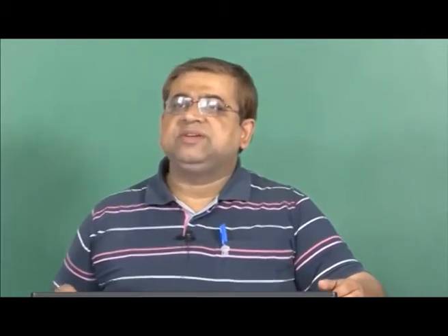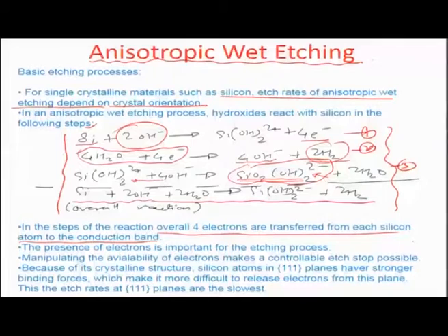So whenever we are performing wet etching using hydroxide chemistry, there is a possibility of eventually the 111 plane to evolve. So let us say if I started in a certain direction, let us say this direction right here is the 100 direction, and the plane perpendicular to it is again given by the circular bracket 100.